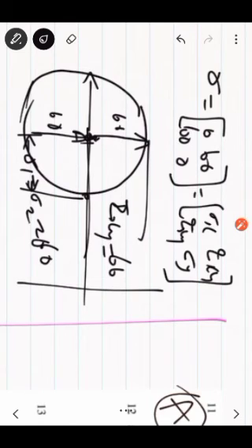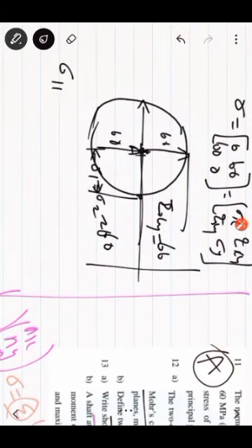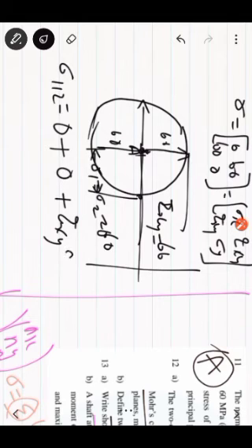So let me calculate this using the formula also. What is sigma 1, sigma 2 equal to? Sigma x plus sigma y by 2, that is 0, plus sigma x minus sigma y by 2, that is also 0. Sorry, let me write the formula first.